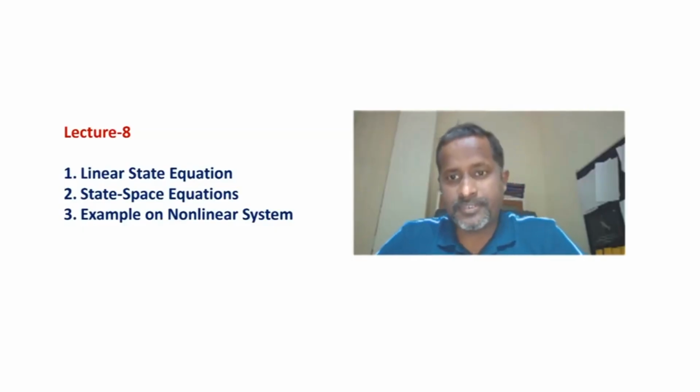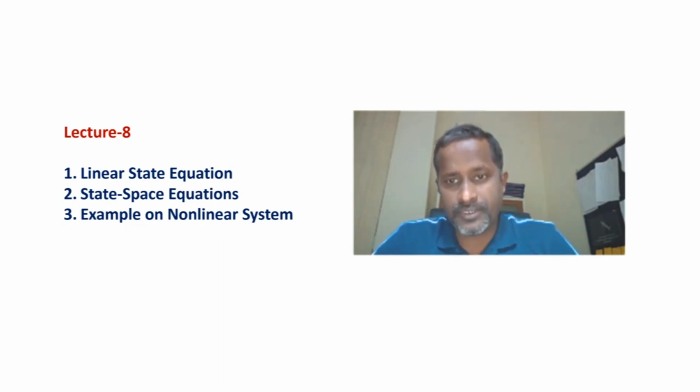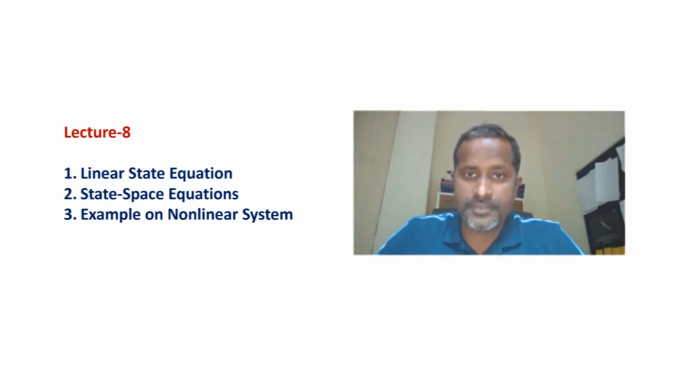In this lecture, we'll be discussing how we can write a higher order system into first order ODE form, and then how we'll be deriving the equilibrium point from those first order systems. After finding the equilibrium point, we'll find the Jacobian matrices using the Taylor series expansion. And from those Jacobian matrices, we'll find the state space representation of the system. We'll have a few more examples on how we can apply this method, then we'll conclude the lecture.